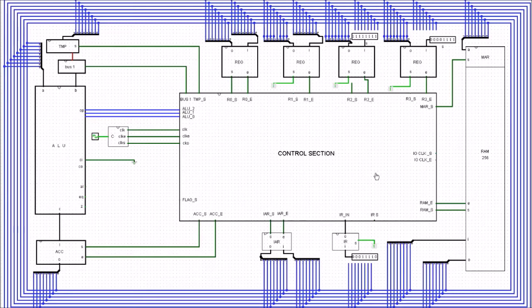So now let's look at the load instruction. The previous store instruction took the contents here and placed it in the memory address which was pointed to with the contents from here. Now we're going to take the contents from the RAM, which is pointed to from here, and put it back into the register here. So it's just the opposite process. We're going to take it out of the RAM and put it into the register.